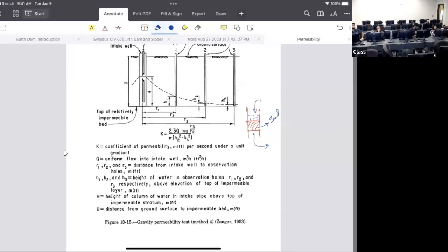And now if we do the same thing in the clay, then what's going to happen? It's going to overflow, right? So for the clay, what we have to do? First of all, we need to stop adding water from the top. The basic idea is take the clay sample, add some water on top, and then come back after 1 hour and see if any water level dropped. If not, come back after 1 day.